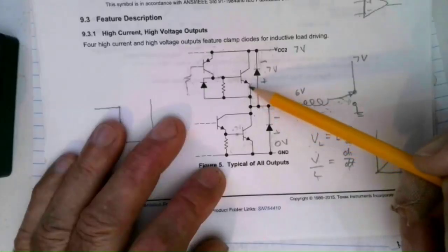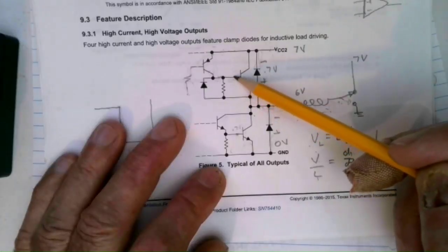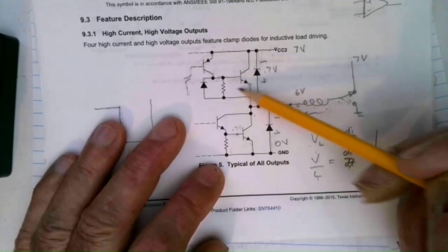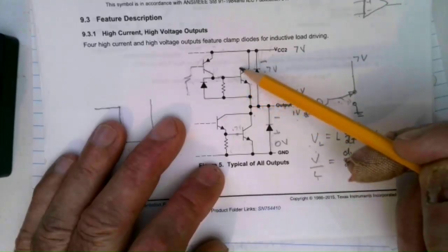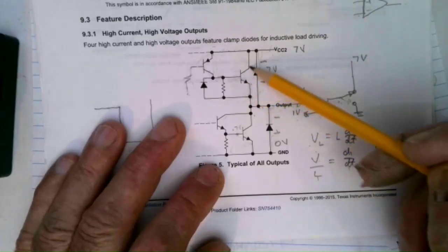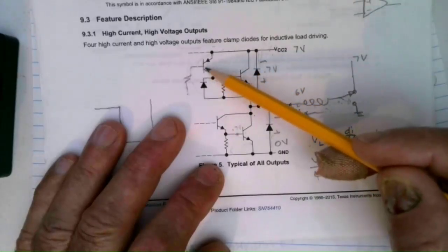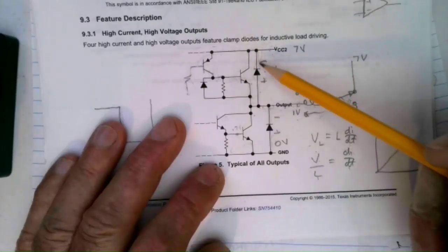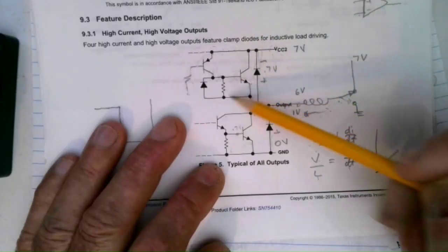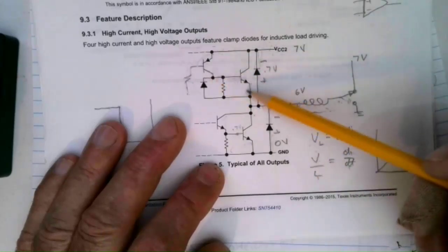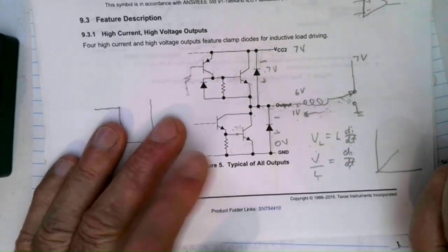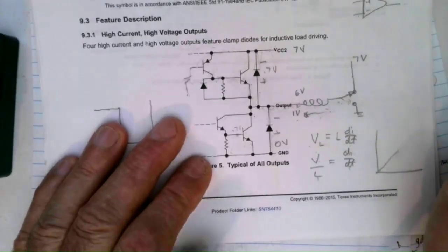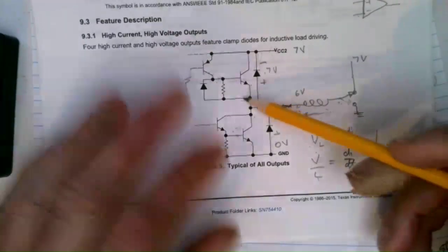And so you can figure maybe this base current here is 10, 15 milliamps or so, assuming the beta of this part is reasonable, because it doesn't saturate again. And then this PNP only has to handle 15 milliamps, not the full load current. And a weak PNP can do that. So on an integrated circuit, sometimes the PNPs are really weak. Anyhow, so I just wanted to show you that